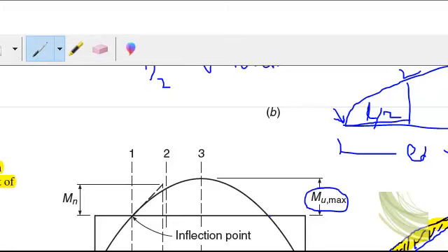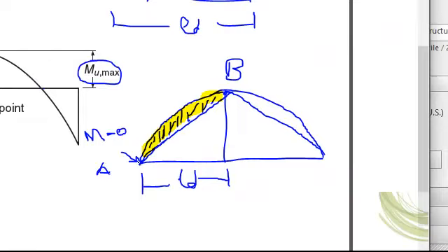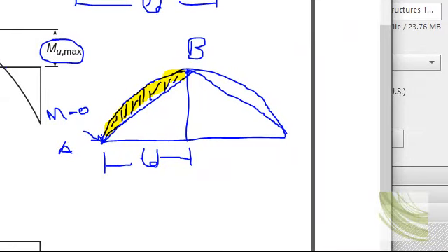So basically to support this, you need to draw your tangent, or your moment strength diagram should be tangential to this one. Okay. This means that it should envelop this actual moment diagram. Clear? Now, this kind of problem arises in this kind of situation, the topic which we are discussing.